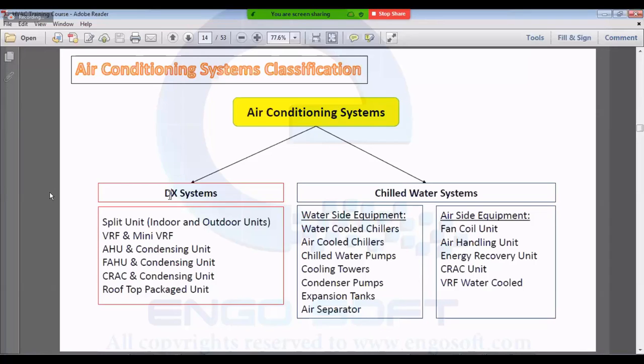Okay. And the supply air is 100 liters per second. So we mix 70 liters per second of the return air coming from the space with the 30 liters per second coming from outdoor, and cool them again and supply them to the space.